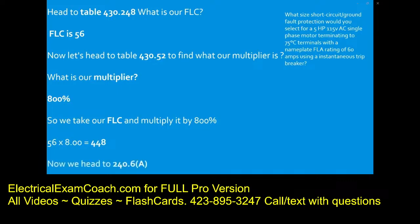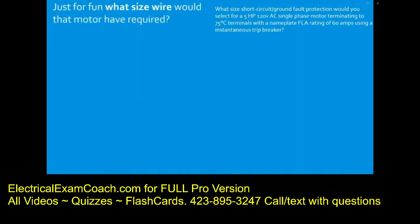Now we're going to head to table 240.6a. We're going to select the next size up, and we're going to select a 450 amp overcurrent device. Now, just for fun, we're going to take this same question and we're going to size the conductors, okay, and show you how outrageous this is.